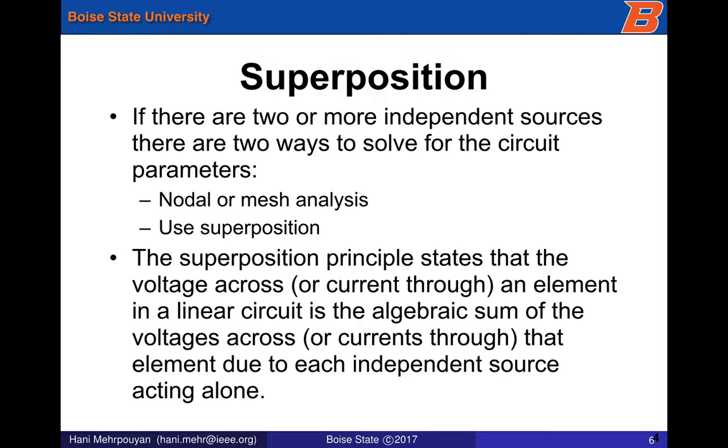But what is very important for us now is to look at the topic of superposition. So we have now come up with the concepts of nodal analysis and mesh analysis, and we can try to solve for different circuit parameters. However, what could be challenging is that as you have more sources, it can sometimes become difficult to apply these principles. So what we will deal with is the principle of superposition, which states that the voltage across an element in a linear circuit is the algebraic sum of the voltage across that element due to each independent source.